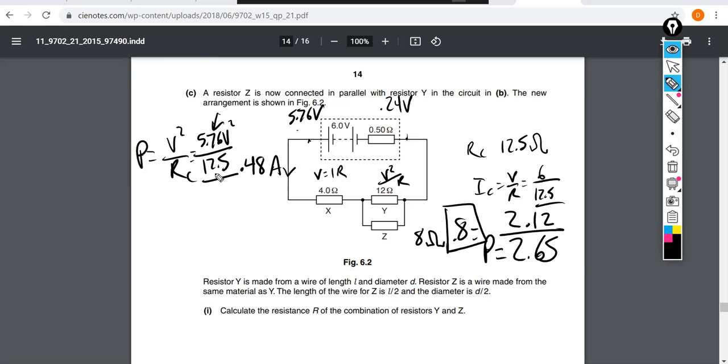And then that's the total circuit resistance. Again, by collapsing this down into an 8 ohm resistor, a 12 and a 24 ohm resistor in parallel make an 8 ohm resistor in series with 4. So there's 12 plus the other half for this one. And so that's where I get the 12.5 ohms of total circuit resistance, very similarly to how we calculated it for figure 6.1 to get the first answer to the current there.